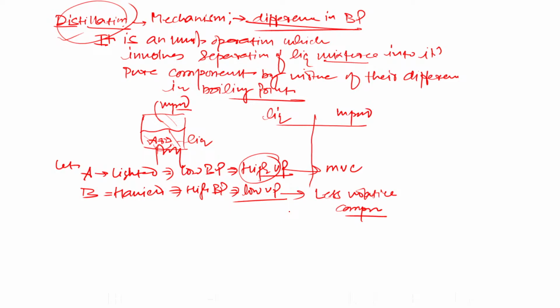So in this case two phases form. We supply the feed, a mixture of binary components, and when we start heating, the vapor phase is formed by adding heat. As we start heating, the vapor phase becomes richer in the lighter component, while the liquid phase becomes richer in the heavier component.